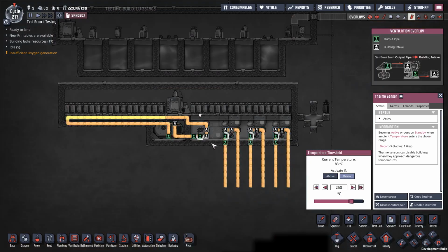And the way I've set up the ventilation is that the input is coming in through this line, and it reaches the thermoregulator and says, if the thermoregulator is on, then I will continue on through the thermoregulator, in which case it comes out the outlet port and continues on its way. And if the thermoregulator is off because one of those 2 conditions is not met, either the coolant is too cold or the room is too hot, then it goes into a bridge and bridges over and continues on its way, right? So if the thermoregulator is not on, this line will bypass the thermoregulator and just continue on its loop.